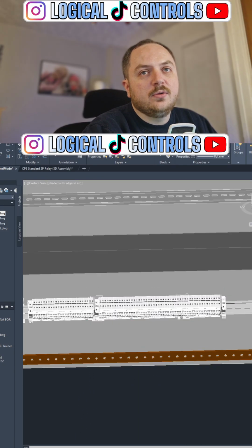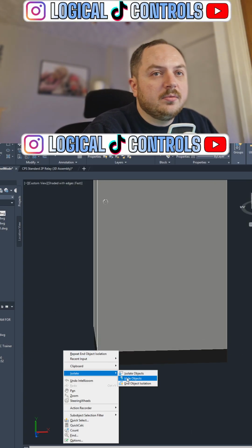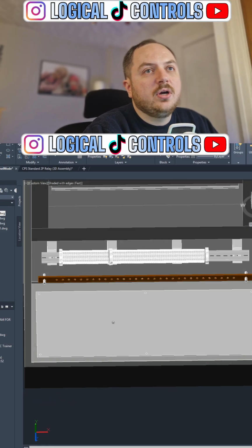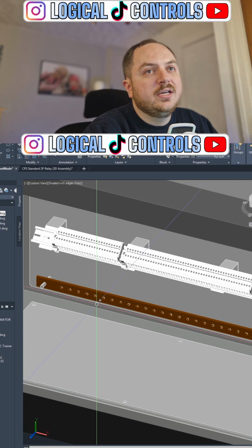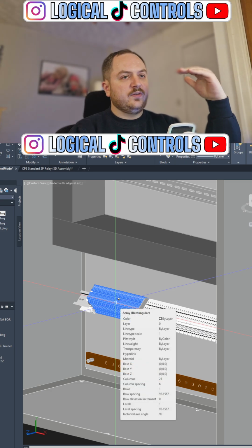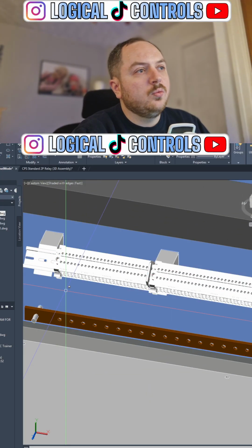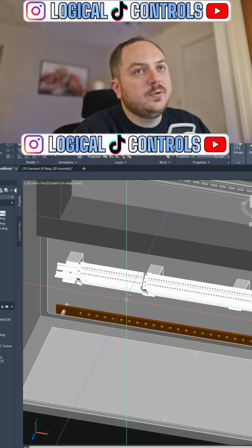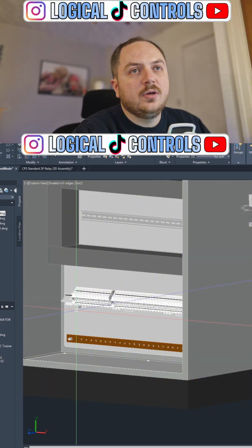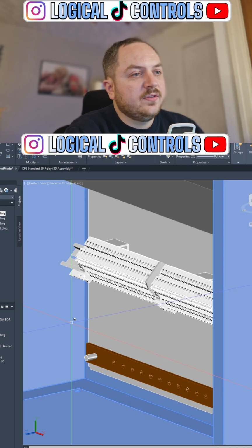That'll do for terminals. I don't want to go too crazy, but if we bring the panel back, the enclosure itself, you can see why I built the brackets. If you're on site, on your hands and knees wiring these field cables, if that terminal's facing you, rather than facing 90 degrees, it's so much easier. It's so much easier for you to put wires in when you can actually see the bottom of the terminal and that sort of thing. So I try to use the 45-degree angles where I can. It just makes life easier for the guys on site.